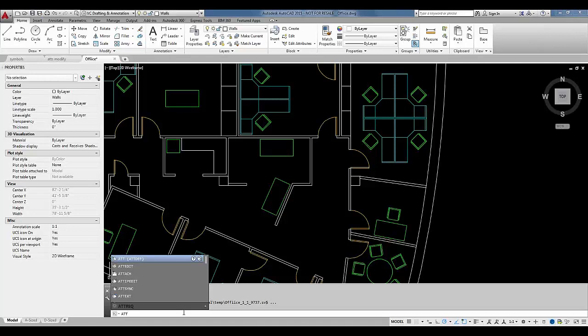And if you're running earlier versions of AutoCAD, so that was a good point, Sean. If you're running earlier versions of AutoCAD, just use the tab key after you've typed in something like ATT. And for each tab, it'll go to the next command or system variable that is related. So lots of little shortcuts available. Anyway, good point. Thank you, Sean.